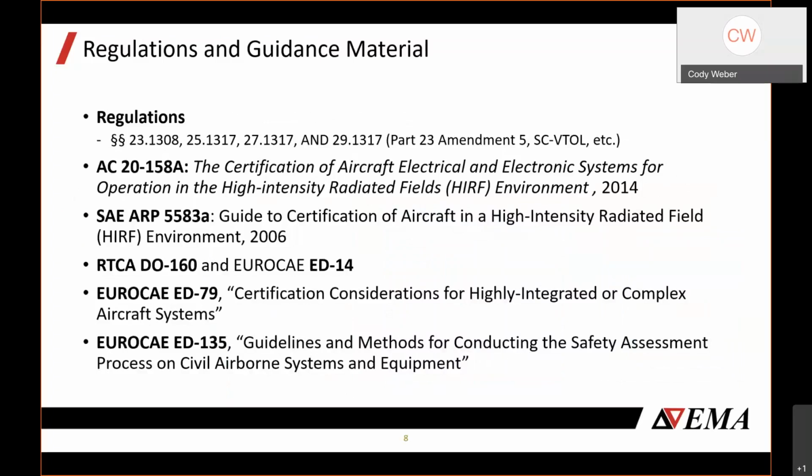Okay, so for HIRF regulations, depending on if you have a Part 23, 25, 27, or 29 aircraft, or even a VTOL aircraft, there's a certain regulation that you must comply with for HIRF certification. There's been some rewrite of Part 23 with Amendment 5 and some of the SC VTOL material, so some of those numbers have changed from what was listed in AC 20-158, but it's a similar approach to the outline that is there.